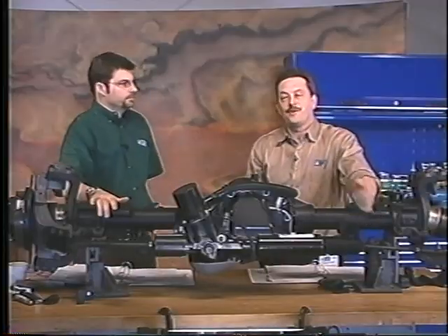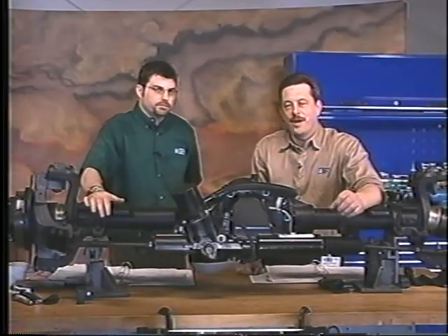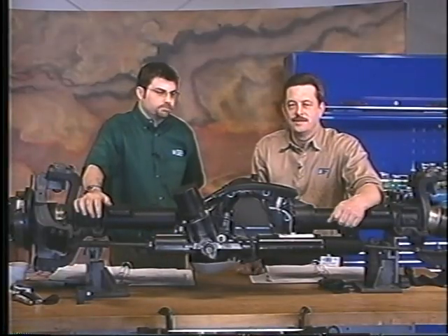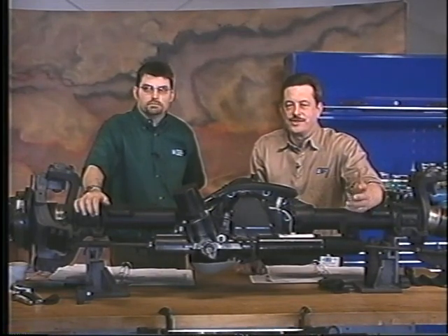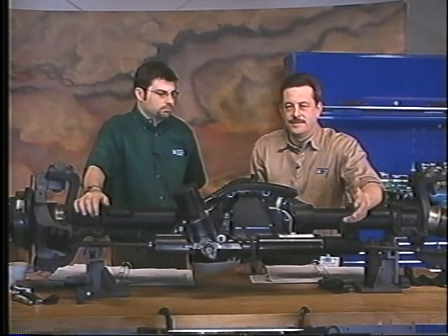All right. Now, a couple other quick tips about the system. Think about this. GM recommends you do not use tire chains on this vehicle. Makes sense. Because when you put tire chains on, you increase the width of the tire, you increase the height of the tire. Now, start turning it, what's going to happen? Well, there's the possibility of making contact with the wheelhouse. That's obviously going to cause some damage. So GM says don't do it. If the customer has to do it, then you've got to take on that responsibility to make sure we only have it in two-wheel steer. Got to keep it in two-wheel steer. That way, we're not moving those rear wheels, and we're not going to cause that damage. If damage occurs, it's not a warrantable situation.